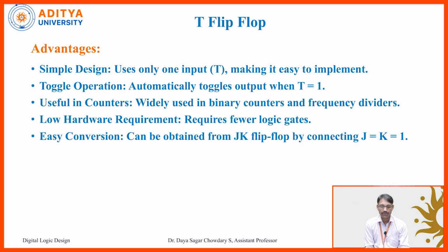Now coming to the advantages of this T flip-flop. The design is very simple and uses only one input, because the J and K inputs are connected to a single input. We call that the T input, making it easy to implement. It has toggle operation, so it automatically toggles the output when T is equal to 1. It is useful in counters, widely used in binary counters and frequency dividers.